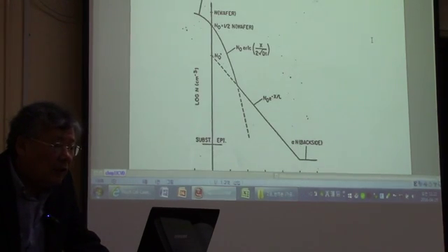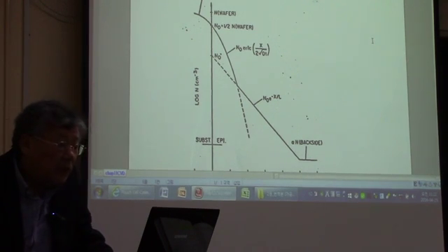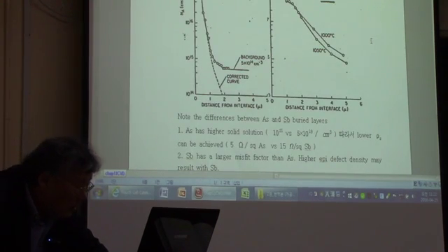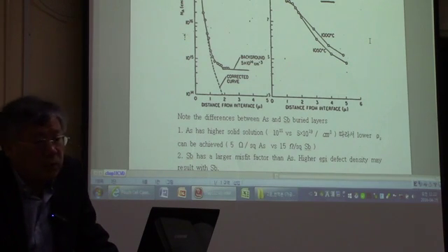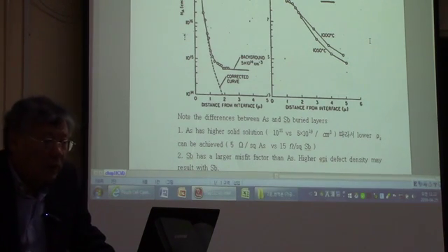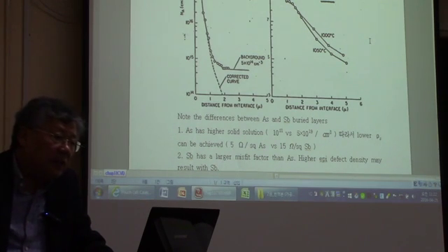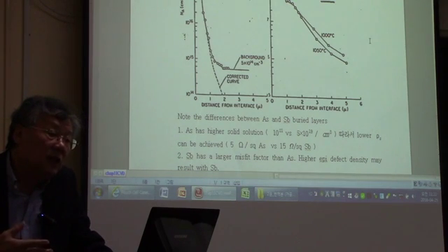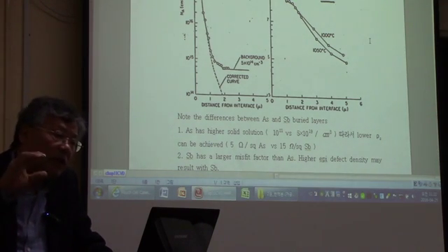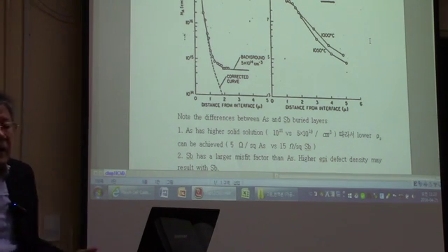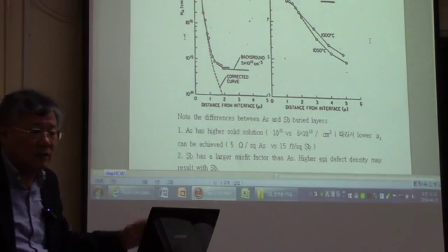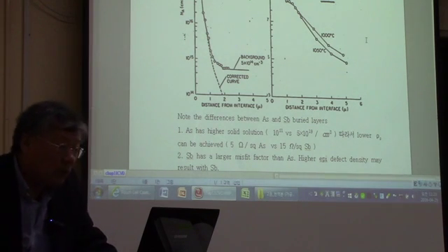So this is the deviation from the ideal profile of the dopants in the epitaxial layer. Now, the small contents of the dopants may affect the electrical properties, or even cause defects in the epi layers. Epi layer is supposed to be a single crystal, but if you have this out-diffusion and the backside autodoping, it prevents you from having a perfect single crystal in your epi layer. It may create the stacking faults, dislocations, and everything like that. Okay, so this is not a trivial question at all.